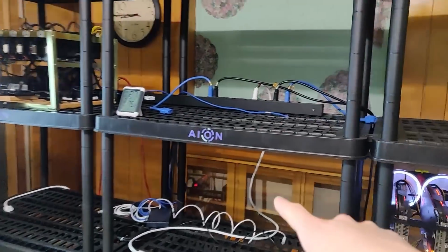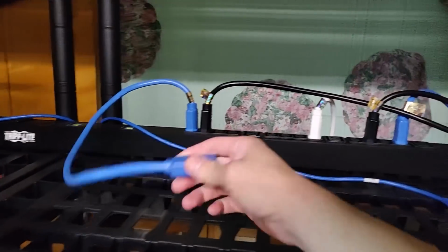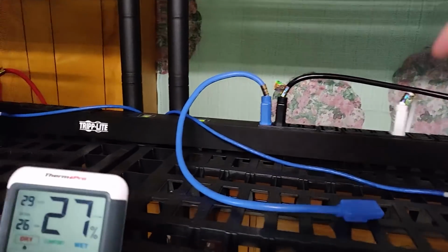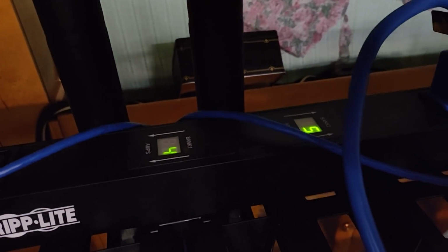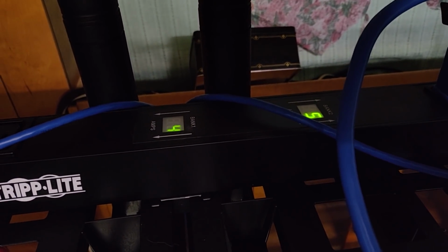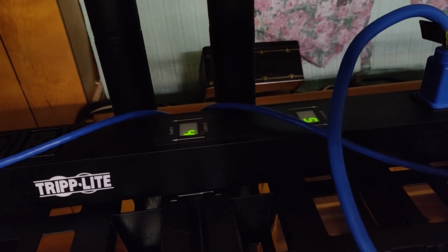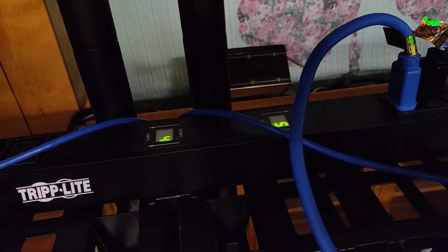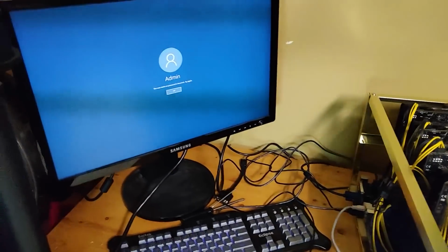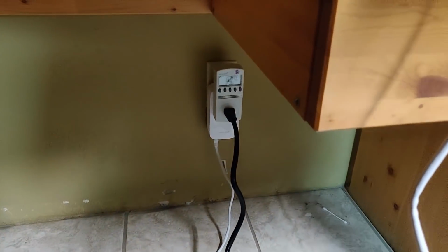And yeah, so where am I going to put this rig, guys? Once the hash rate is going, I'll probably put it on top here so that I can utilize the short PDU C13 to C14 power cables, and I already got a network cable here. As you guys can see, I already have about 9 amps being utilized out of about 24 amps safely, so we can add a good bunch more, about 15 amps more onto this PDU. So with this EVGA P104 rig, we will see how much power consumption we're going to be utilizing on the watt meter there.